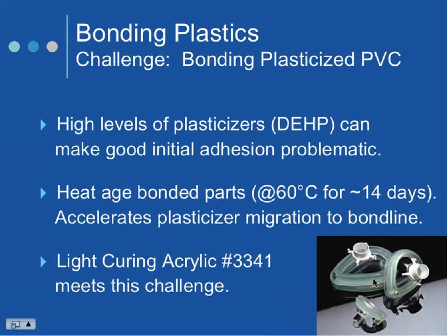We really don't like to get rid of it. It takes incinerators, scrubbers, very expensive. But there has never been a perfect or direct one-off replacement that I've seen. Anything else out there is quite a bit more expensive. You have to treat it in order to bond to it. So I don't know what's going to happen with PVC, but what we ran into a lot was the DEHP, or the plasticizers, the things that make it nice and flexible, were the things that gave us trouble because they have a way of migrating up into the bond line.